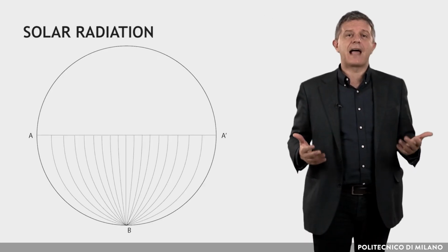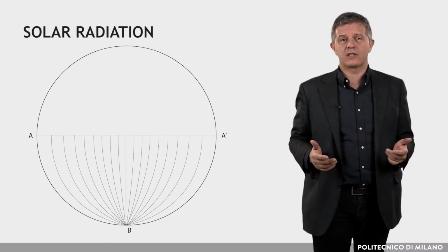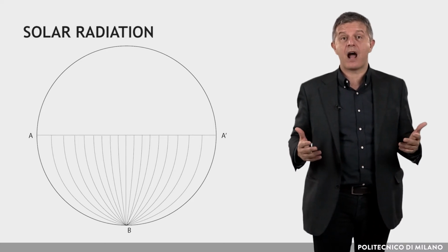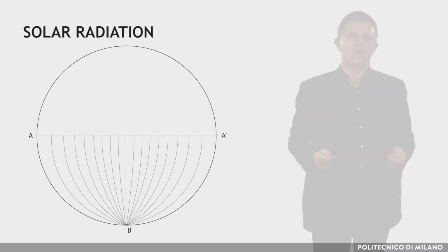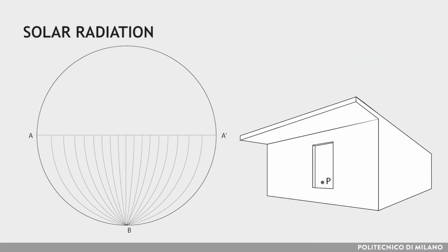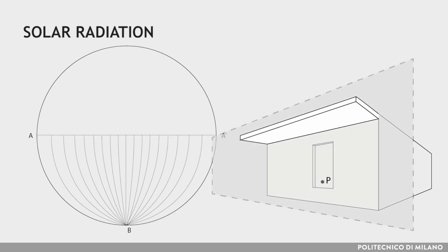The vertical curved lines, which are the extensions of the concentric semicircles contained in the upper half of the diagram and converge at point B, take into account the influence of shadows created by horizontal overhangs with edge perpendicular to the facade. These lines are identified through the calculation of the angle sigma lying in the plane of the facade and formed by the horizontal line passing through the point P and the line joining P with the terminal point of a horizontal overhang or with the upper limit of a vertical overhang.